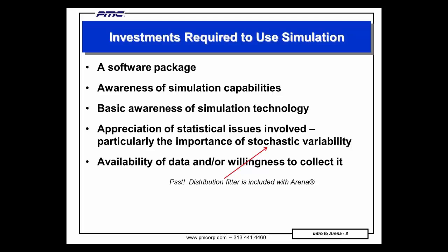Now, processes, the first key ARENA concept, they're represented by a process block in ARENA. For convenience in interpreting output, a process may be classified as value-added, non-value-added, transfer, wait, or miscellaneous. Entities move through the model. As mentioned, an entity represents whatever the modeler desires.